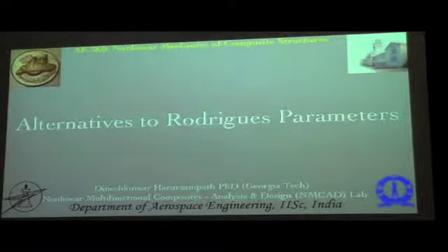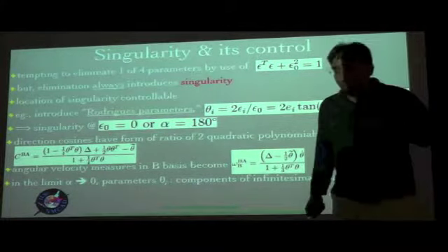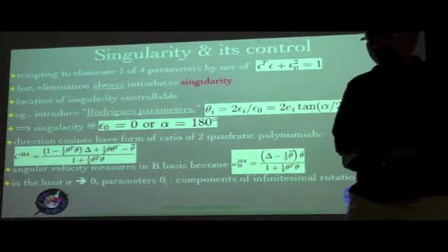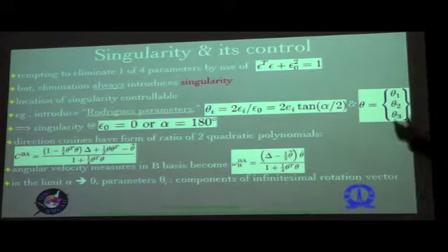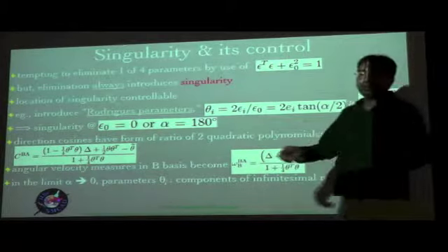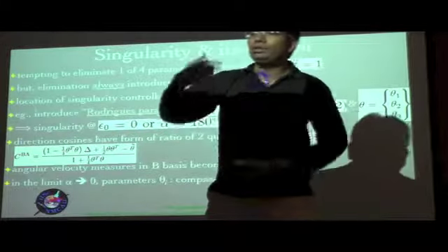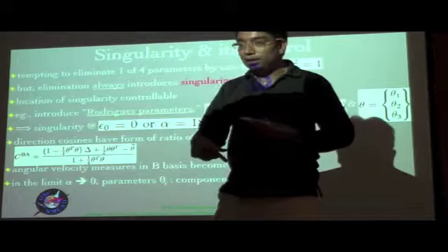Sir, so that order does matter in rotations? Yes. Meaning that superposition is not valid. Exactly. So basically the commutativity is not there. You rotate about one direction and then about another direction. It's not equivalent to rotating about the second direction, then coming and rotating about the first direction.